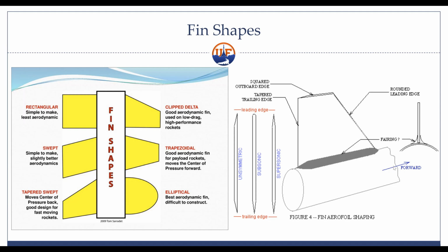The last thing you have to consider is the fillet between the fin and the body. If you don't add that to your rocket, you're reducing the strength significantly, because what can happen is fin flutter. Basically, a fin goes really fast and can start oscillating like this, and eventually if it oscillates too fast, it just snaps off, and that's not very good. You should search up a video about that. Unfortunately, I don't have enough time to show you guys, but it's a really important effect that you should take into account. I think both teams do, and I think Matt worked on a simulation for that too.